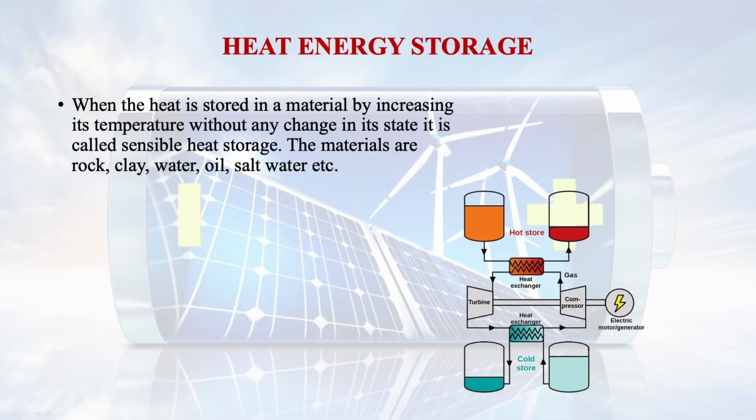And coming to heat energy storage, we know the passive heating system, which we discussed when we discussed renewable sources of energy from sunlight and so on. We know that this passive heating system is a major heat storage technique, and when heat is stored in a material by increasing its temperature without any change in its state, that is called sensible heat storage. The materials used in this storage system can be rock, clay, water, oil, salt water,